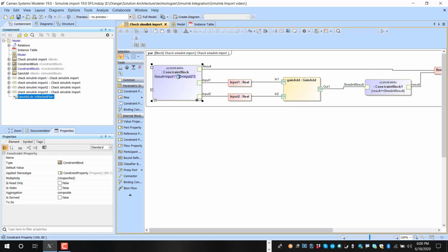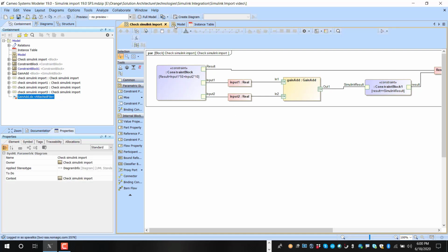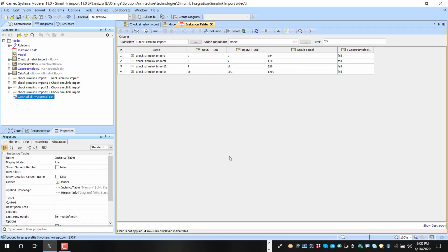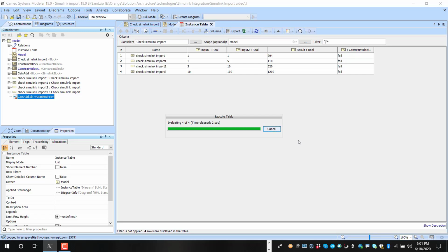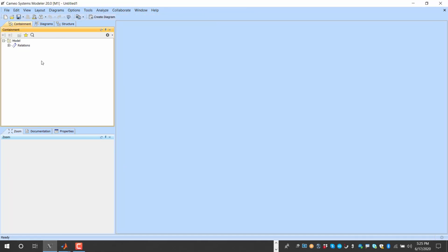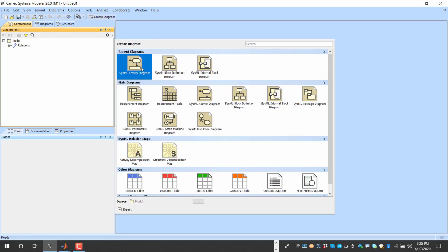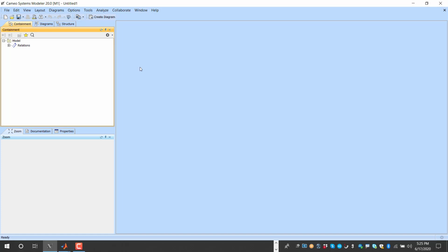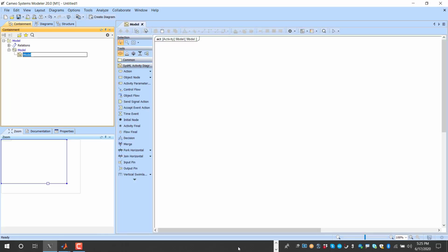And here we will change the logic, because if we run now with the current logic, it would fail the test. So we change the logic and we'll re-execute those tests. You see, we are running without behaviors because that executes the Simulink model as a black box, without behavior inside. The behavior is inside of the Simulink model, but it's actually another thing how it executes it. It executes it with inputs and returns a result.